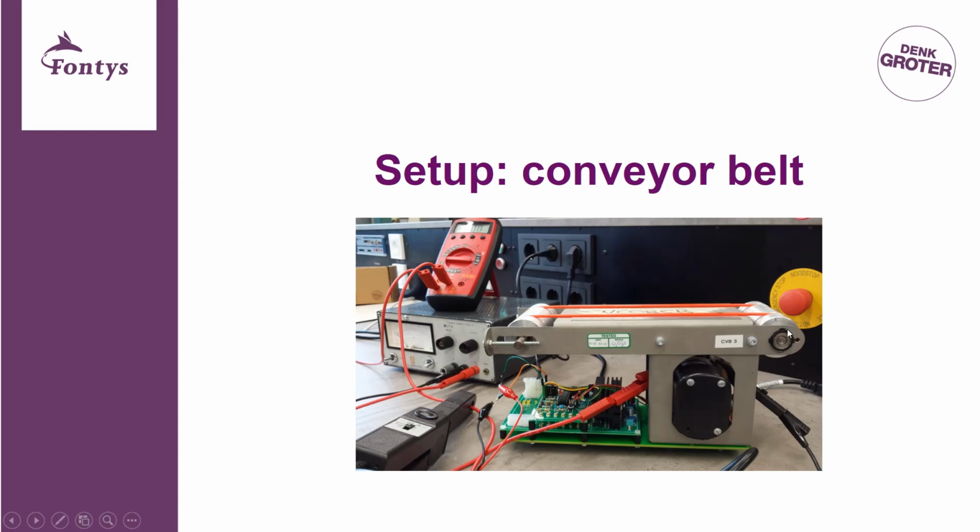So we are going to measure two things. The motor current, we do it by a current measurement device over here, or you can use an inductive current clamp. And we are going to measure the frequency of the encoder by means of a frequency measurement device, or you can use an oscilloscope for that. And we are going to change the speed in several steps by changing the motor voltage, so the voltage towards the motor. And these steps in voltage don't have to be equal values, but we need a couple of measurements in order to get a good measurement result.